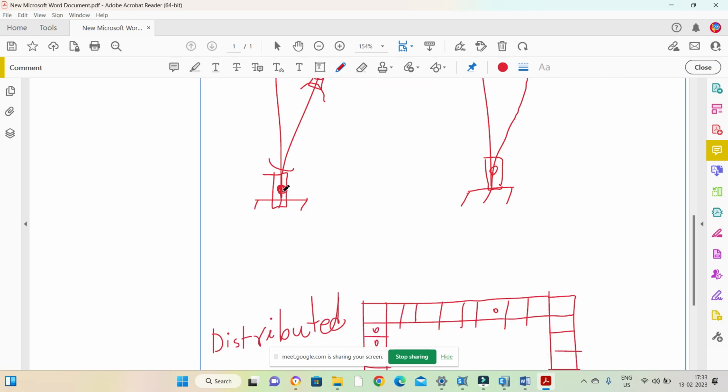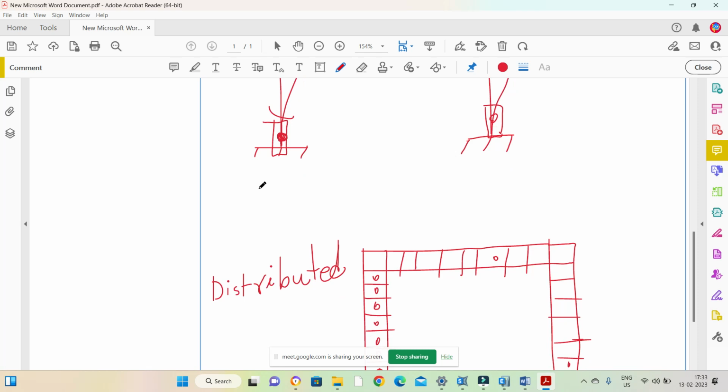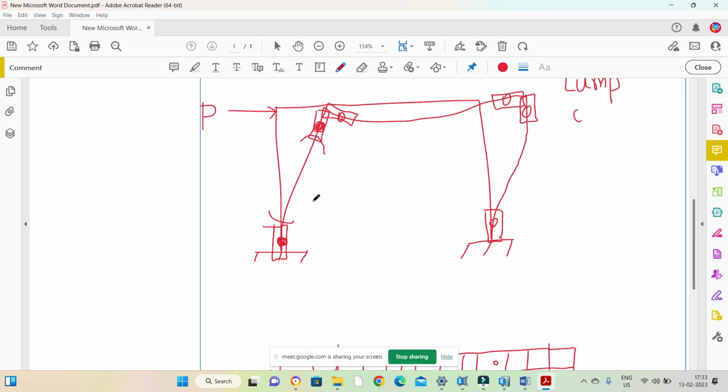And now let's see how to define the hinges. Hinge is nothing but the capacity of the structure in terms of load and deformation, which again we define for a particular member.